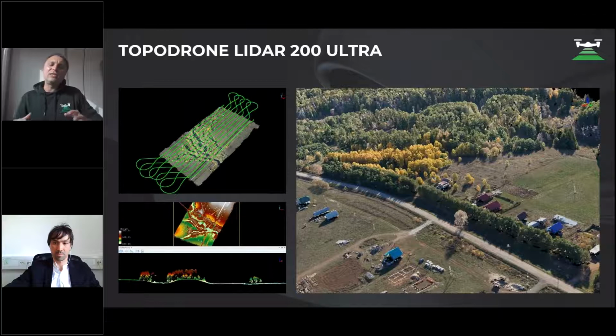And as you can see, it is better to see the point cloud in RGB colors. This is why we had to find a solution to combine the LiDAR point cloud together with photogrammetry data and to colorize this point cloud. And this is why we chose 3Dsurvey, not only because of the opportunity to colorize the point cloud, but because of the wide tools to vectorize data,